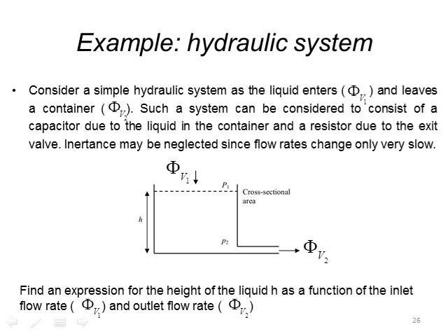Now we can do an example of using lumped modeling, using our capacitance, our inertance, and our resistance, and Ohm's law, and also the equations of the differential change of the pressure and flow and capacitance and also the inertance.